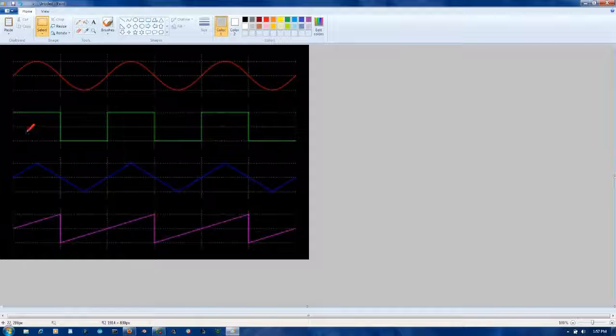But the digital signal is basically either on or off. Once again, think of this as voltage. This is our voltage scale. The bottom here is 0 volts. The top is 5 volts. And this is time as we move across. So you see, as we move across time, we're at 5 volts, and then boom, we jump down to 0 volts. And then, we hit a time period and we jump up to 5 volts. This is digital. Digital is on and off.